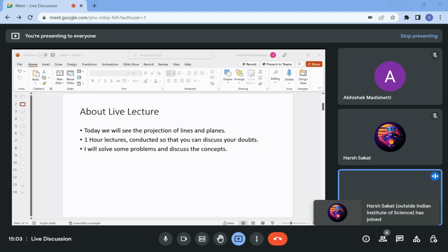When do you see the true length and the true angle? True length and true angle with respect to HP will only be visible in a plane that, so this is the horizontal plane, satisfies two conditions. It is perpendicular to the horizontal plane, so the plane should be vertical here, and that plane passes through the line that we are considering.